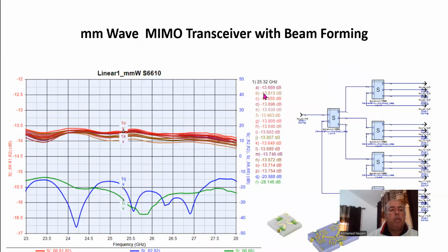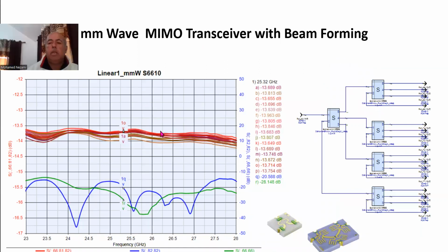Now for the passive, I need a 16-way divider and summer, and that's basically here, okay? And this was designed in the last session. I think we went through this. So basically what I did is I use a 4-way divider from Mini Circuits. I apologize, both companies make the same device, but I believe this is from Mini Circuits, okay?